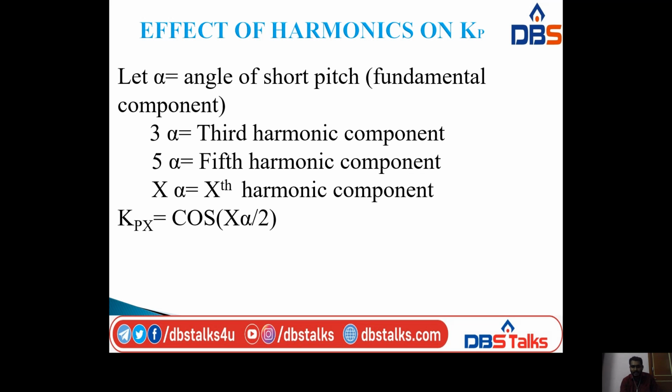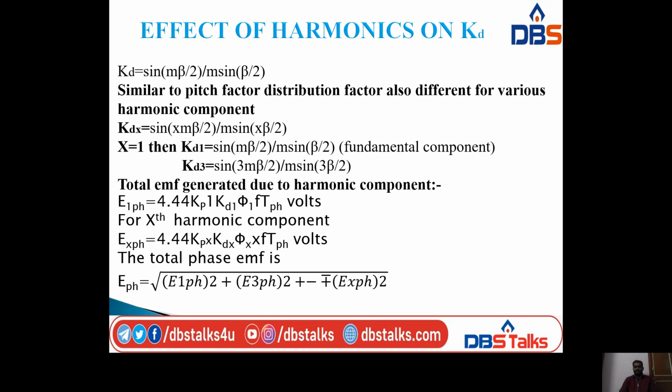Okay, and next I am writing distribution factor. There is the effect of harmonics on distribution factor. You know the formula for the distribution factor, Kd is equal to sine m beta by 2 by m sine beta by 2. Similar to the pitch factor, distribution factor is also different for various harmonic components.